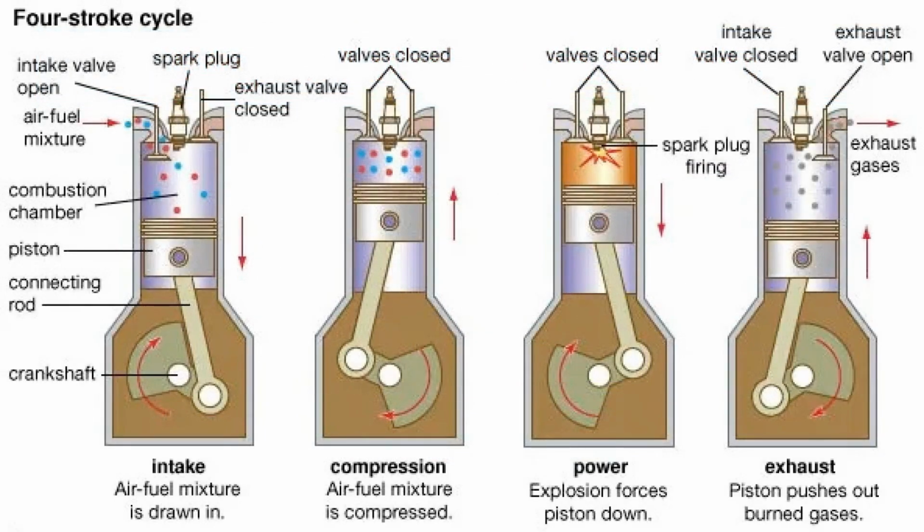The second important factor for the lubrication system is timely cooling of the oil heated up inside the power unit. If this is not done, the lubricating properties will decrease as the temperature rises, which threatens to overheat the engine. Existing methods of lubricant cooling: open crankcase ventilation method, crankcase cooling by closed ventilation method. In the first method, the gases formed in the crankcase are discharged into the atmosphere through a special hole. In the second case, the gas is directed back into the cylinder, where it is safely burned.